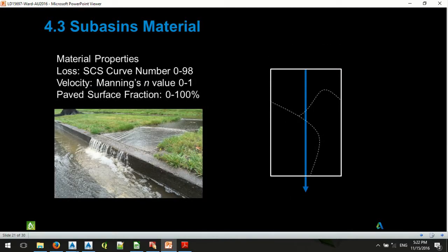But in addition to those, the hydrograph can be tweaked with what I call the minor factors. They're the material factors of the sub-basin. As you can see in this example image, water moving across a hard, smooth, impervious surface moves a lot faster with more volume than water that flows across a very soft, pervious surface.